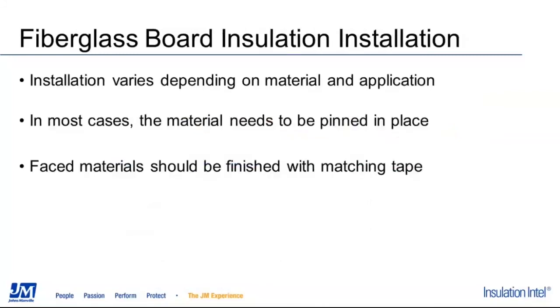So how to install this insulation? Installation will vary by application. In general, it will be pinned in place. And if you're dealing with a faced product, we would recommend finishing and covering the pins and the edges with a matching tape, both for great aesthetics and also provide you with continuous perm rating for the whole system.